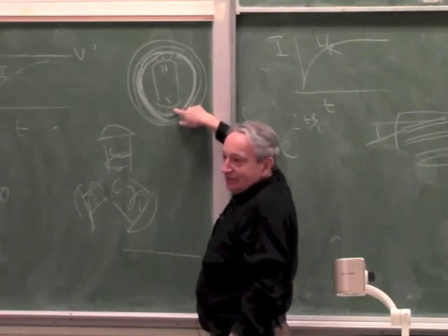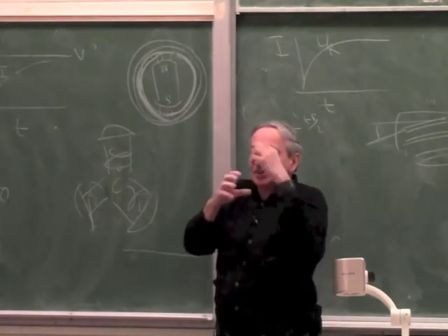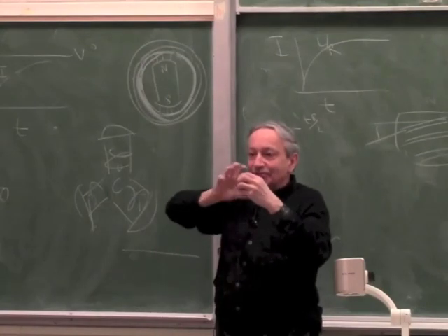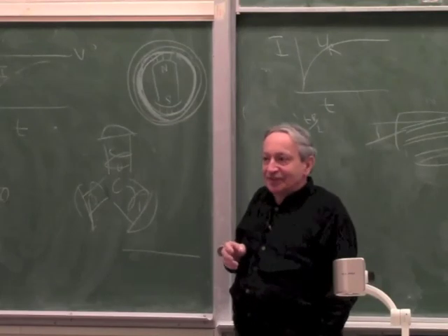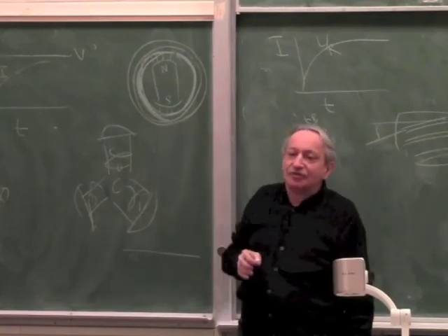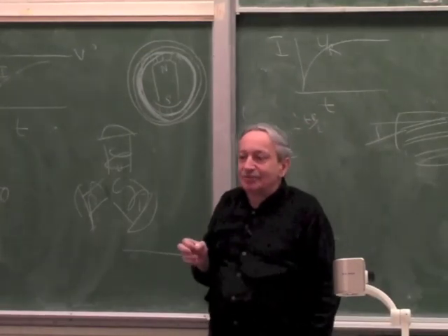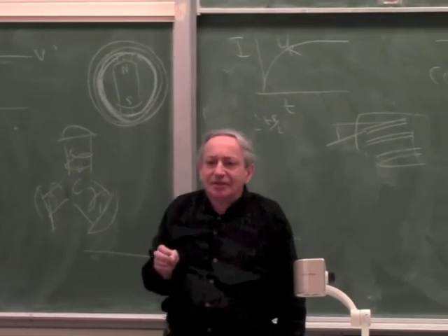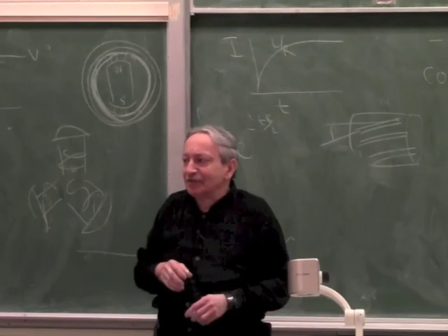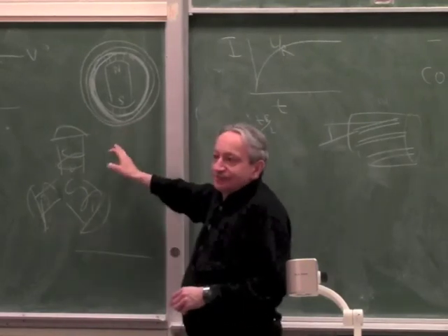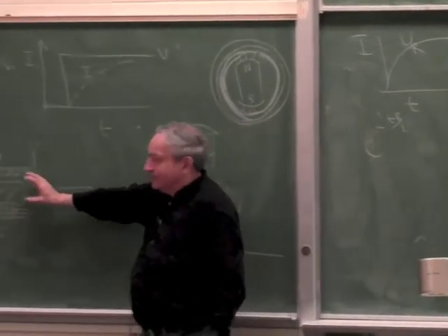Okay, is that clear? So is the geometry clear? Imagine a teacup that has a magnet on the inside, a ring of steel on the outside, and the teacup can rotate in between, but the teacup is made of winding. So this is the most popular construction for a high-performance DC servo motor. For example, the motors made by Portescap, or all the standard names of when you buy a high-performance DC servo motor are all a bit like this. Okay? It has some limitations, of course. It's weaker. The armature is weaker.